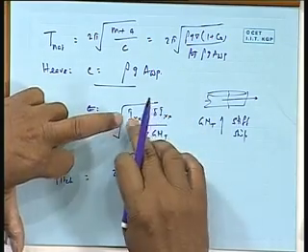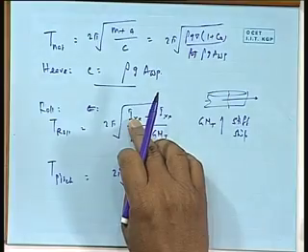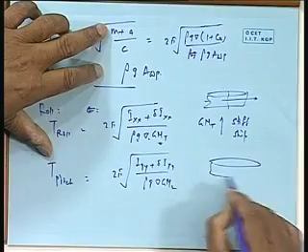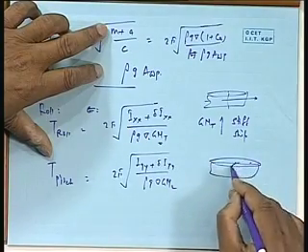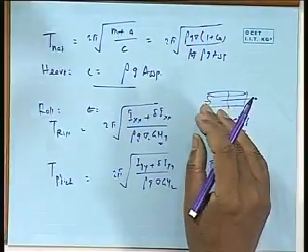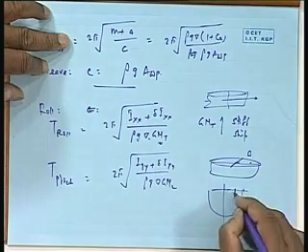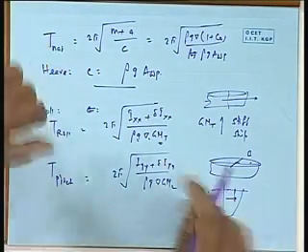I_xx is very small. I_xx is mass into moment of inertia. Mass is given by the displacement. The radius of gyration about the x-axis will be about 30% of the breadth. Because if you take a ship here, and take a moment of inertia about this line, this is my B here. All the hull is on the side. You can approximate it to be between 25 to 30% of the breadth, because the moment of inertia will lie somewhere approximately at this kind of distance. If you rotate that, it is between a solid cylinder and a hollow cylinder.